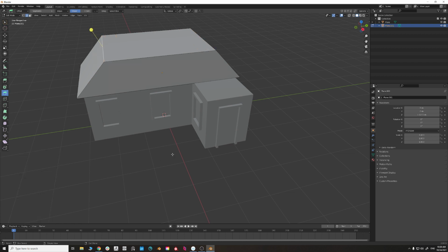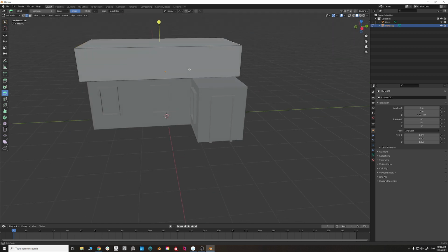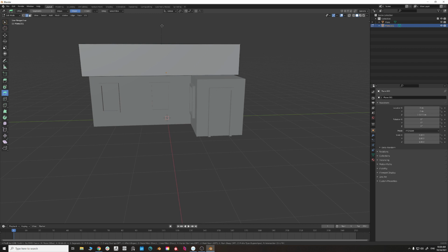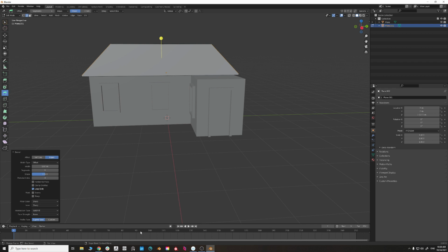Yeah, so I'm going to press and do a bunch of times. And I'm going to go to the edges, and I'm going to try to give this a nice, sort of like a nice taper over here. I'm going to use Bevel on these to create the taper. Yeah. We're going to add a whole bunch of segments, like maybe 14. And we're going to reverse the profile to make it something like this.